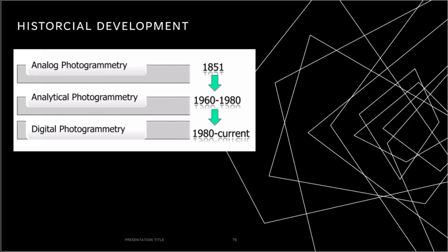Analog photogrammetry consisted of first-generation stereo plotters in 2 types: direct optical projection instruments and then instruments with mechanical or optical mechanical projection. It creates a true 3D stereo model by projecting transparency images through lenses. The model is formed by intersections of light rays, left and right, which we will call L&R. Direct projection of light rays by mechanical or optical mechanical means is aimed at in this analog photogrammetry. And then the output from this process was topographic maps.